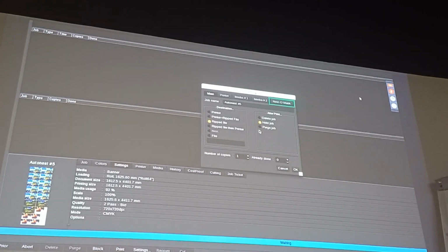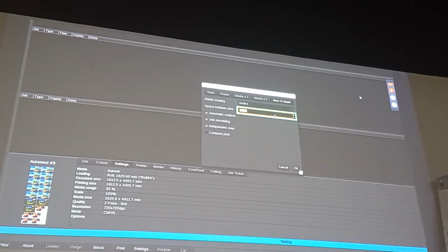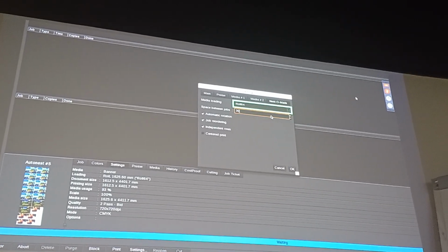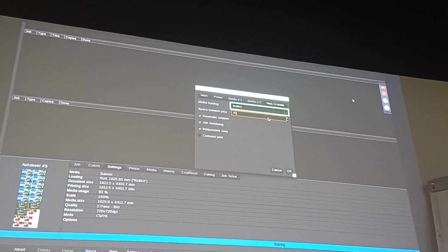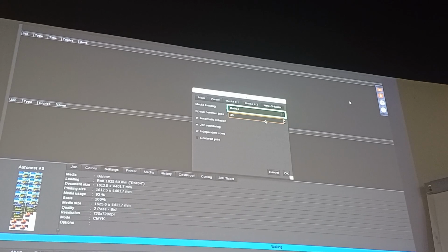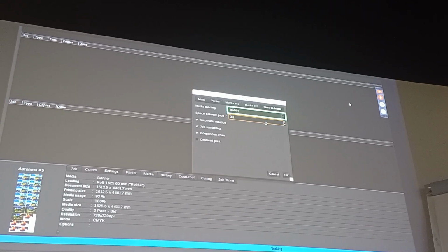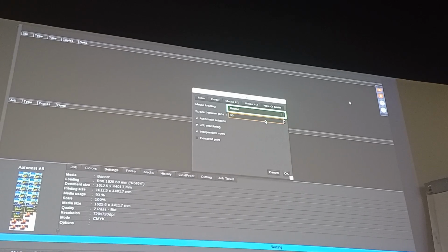By going in the Nestomatic tab, you can also do last-minute changes to the current layout, like setting another margin between each image or switching the media size, for instance. Be careful, if the media size is too small and some images don't fit any longer, these images will be removed from the AutoNest file and there is no chance to retrieve them unless going back to the print module.